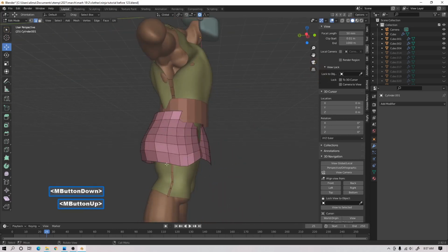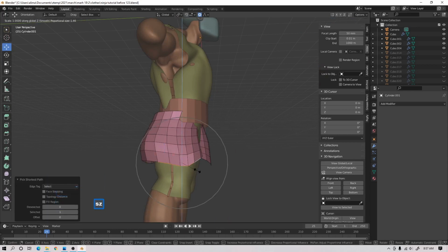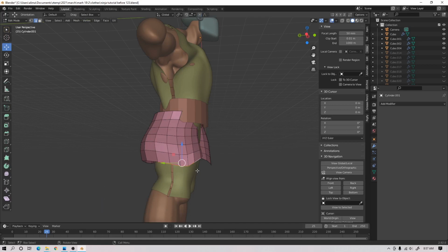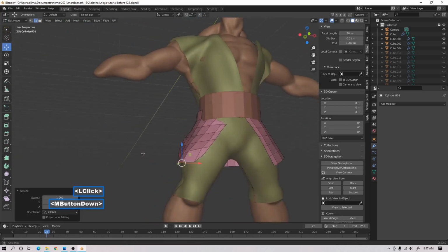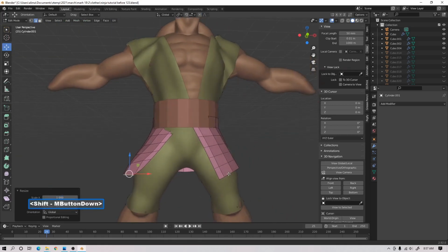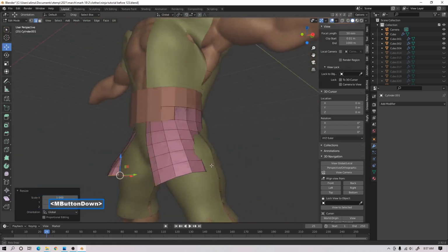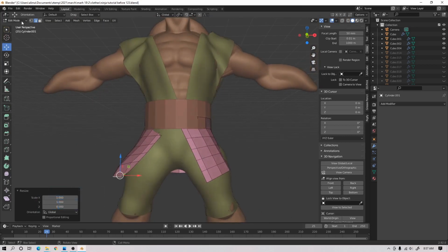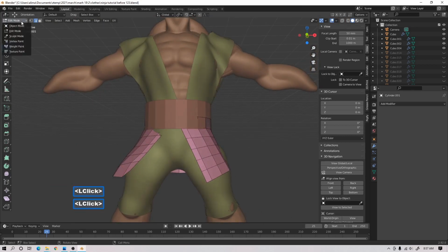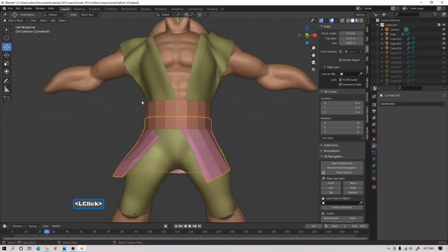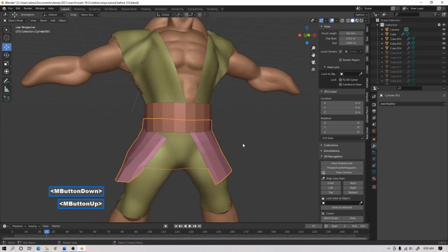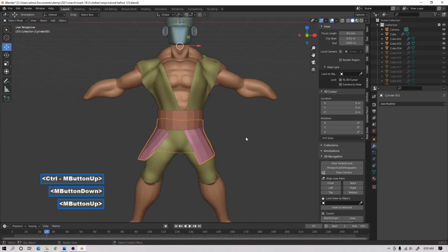Do not like how this is looking, so I'm going to select here, hold Control, select there, press S to scale on the Z-axis 0. Oops, I'm going to press O to turn off proportional editing. S to scale on the Z-axis 0, and what that does is flatten things out. That's what I just did there. As I'm looking at this, it's probably easier to adjust this in sculpt mode. So I'm going to deselect, let's go to object mode, take a look at this, hold Control.